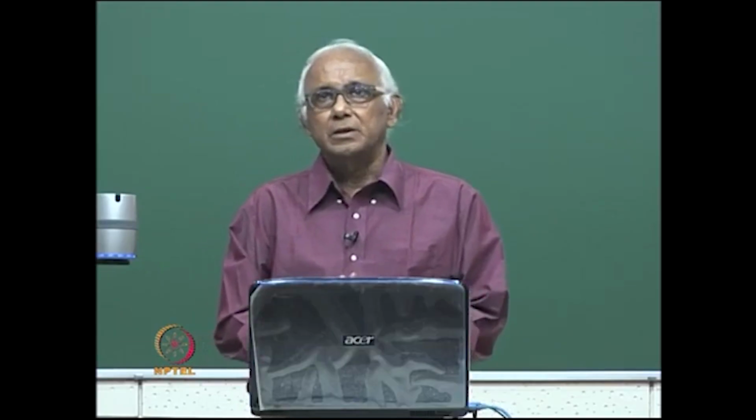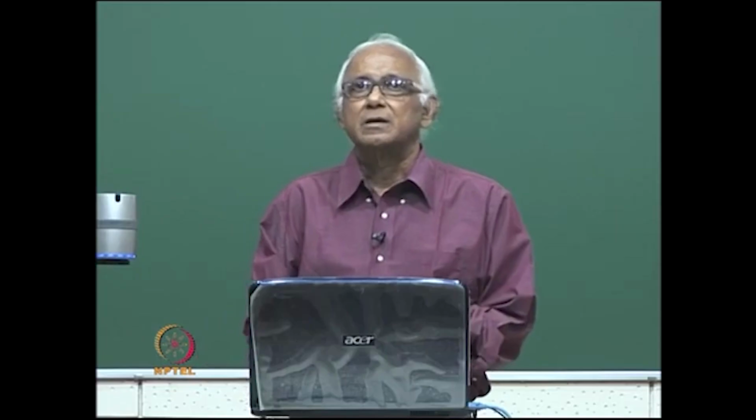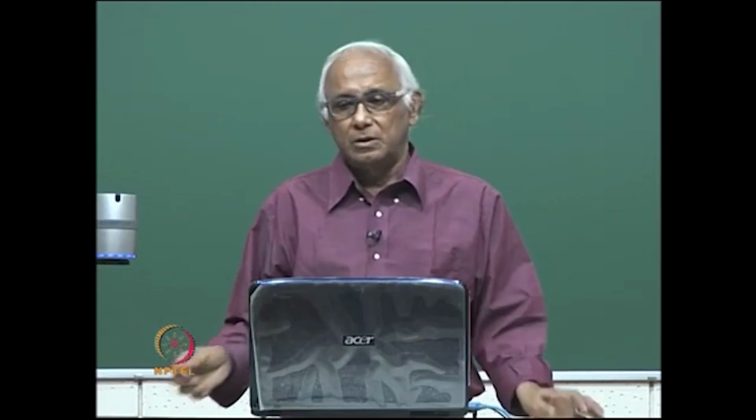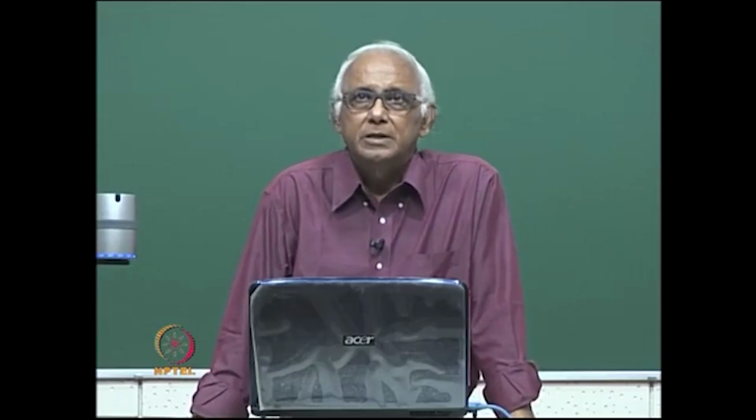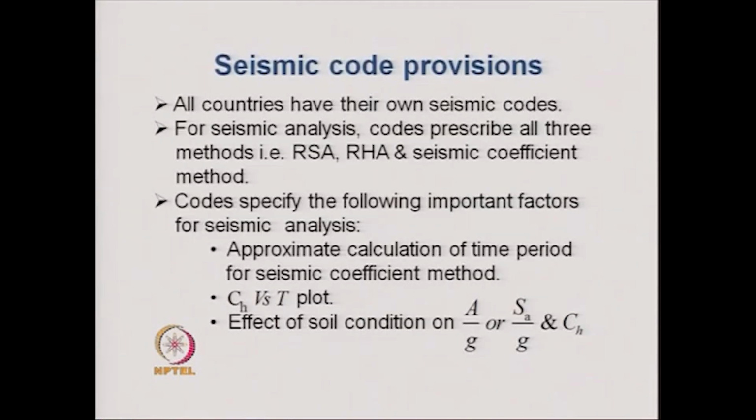The seismic coefficient method as such has certain limitations, in the sense that it does not take into account the participation of all modes of the structure in the response. Secondly, it is based to some extent on empirical formulas which are difficult to support completely theoretically. However, the basis of those formulas can be justified to some extent. In spite of that, the seismic coefficient method has been found to be very popular with engineers.